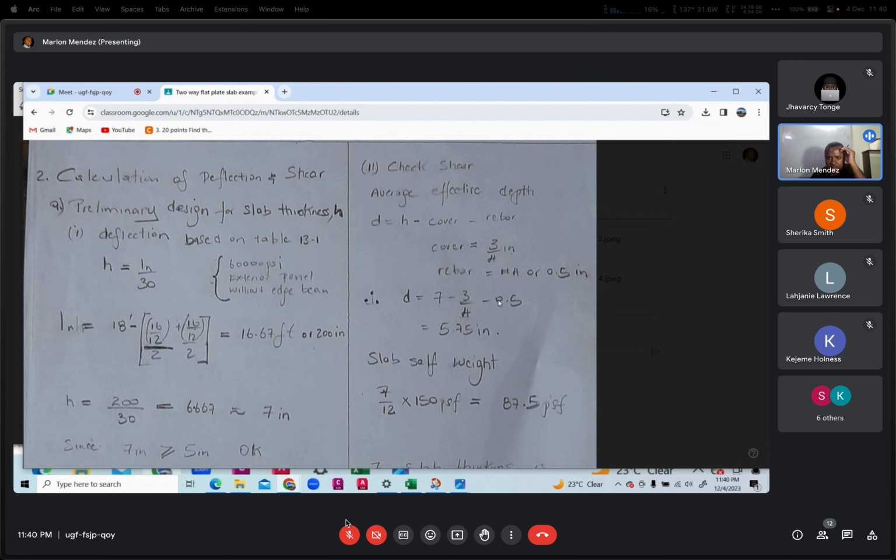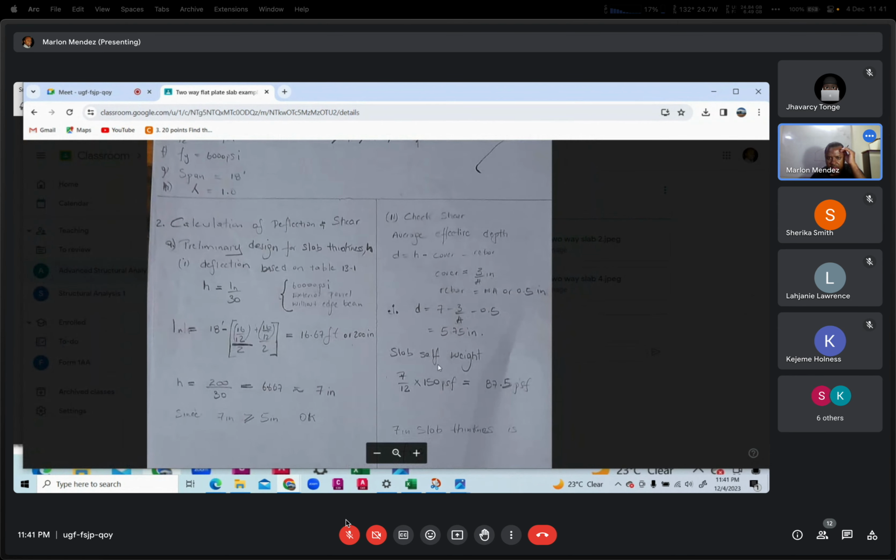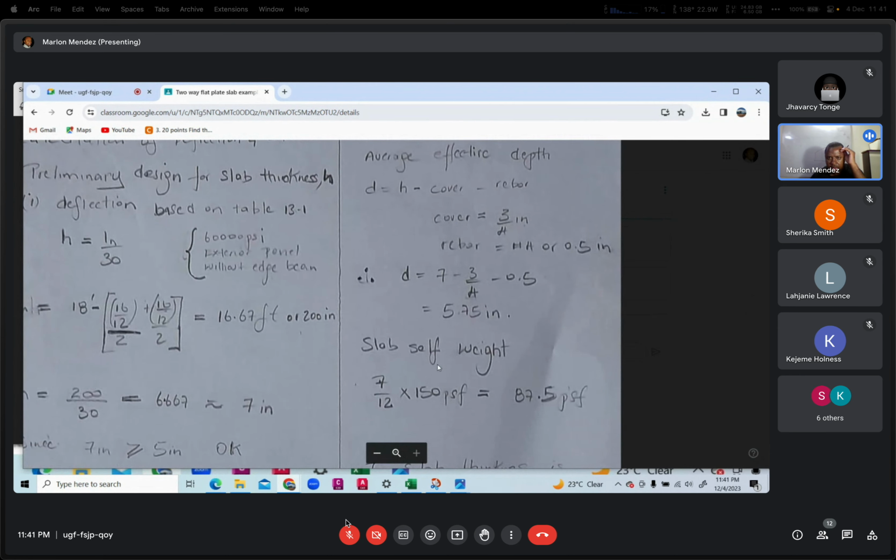3, and the rebar is half inch. After you remove that, normally it's the center of the rebar. So you could divide that by 2 and subtract, and you get the center. Even though I said divide by 2, no, don't divide by 2, because you're dealing with 2 layers of steel. Then in essence, it's actually 0.5, if you understand what I'm saying.